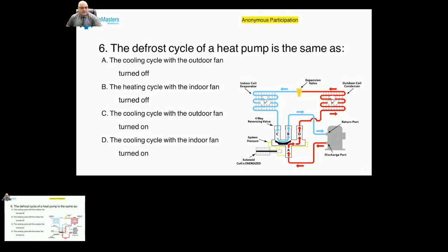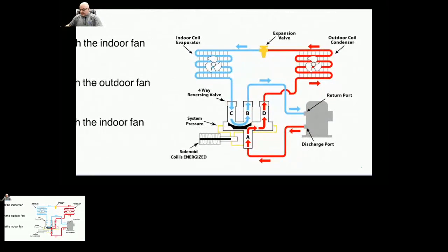So 16 participants answered out of 20 who were participating in Socrative. And yes, you're right. The correct answer is A. So when you are doing your defrost, you're technically using the outdoor coil as a condenser, sending hot refrigerant to the outdoors, and you're stopping the fan, because working the fan is just going to cause meaningless heat loss for you.